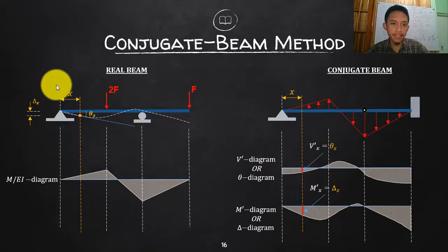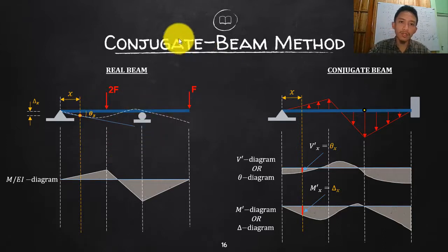Okay, so for example here, this is your beam that is originally supported, that's this length, and that is the orientation, originally supported by a hinge and a roller somewhere there on the length, and that is a cantilever or an overhanging beam. Okay, so the question there is, let's say for example, you want to get a deflection or rotation somewhere at any point here in your beam. So how do we use your conjugate beam?